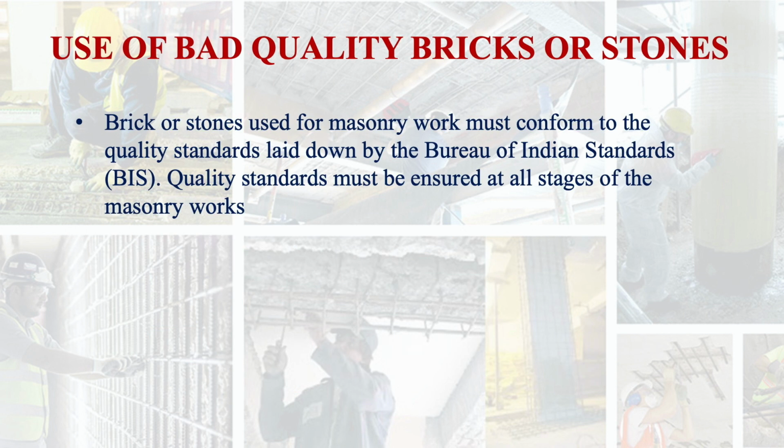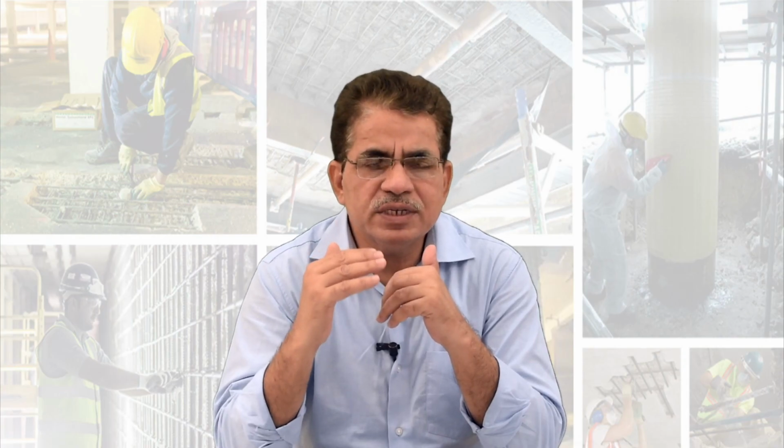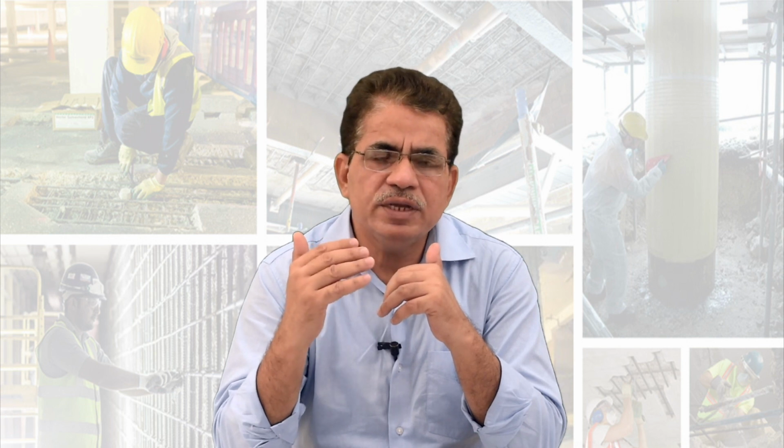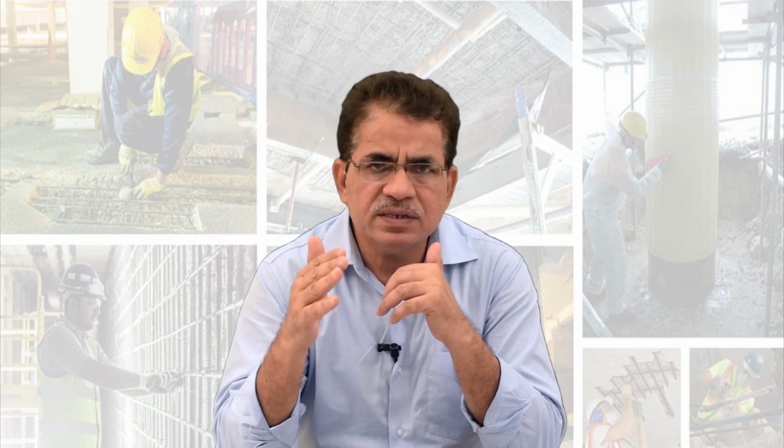Use of bad quality bricks or stones. Bricks or stones used for masonry work must conform to the quality standards laid down by the Bureau of Indian Standards. Quality standards must be ensured at all stages of masonry work, because if we use substandard or poor quality material, then certainly it is going to be affected by environmental and other factors, and there will be problems in the structure.